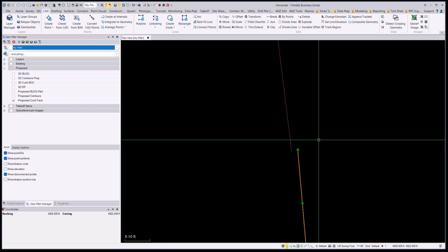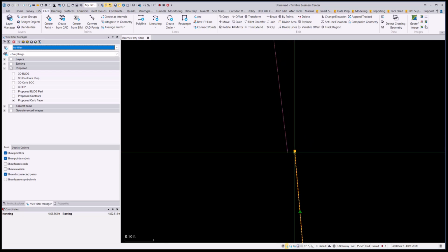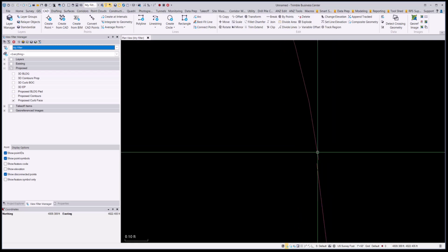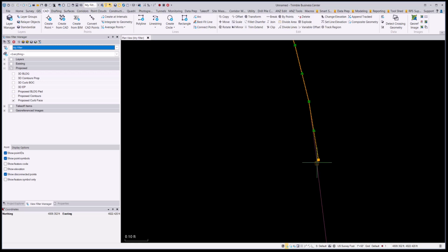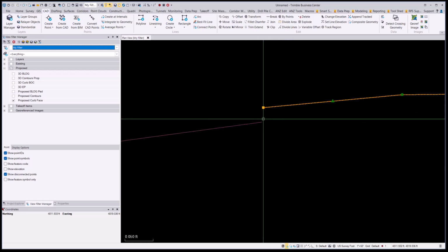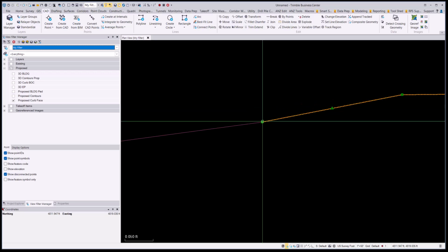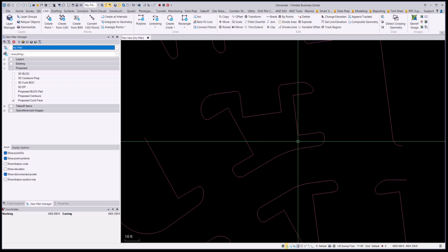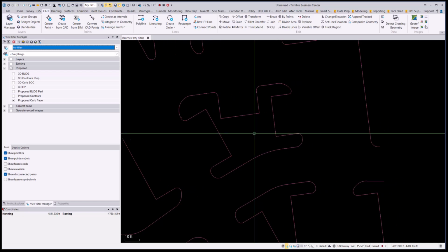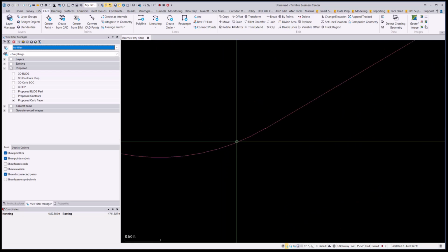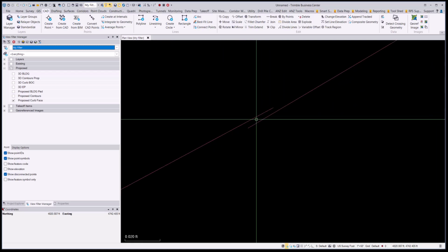So if I wanted to, I could go through all these and I could drag and use these grips, and I could snap these together. And so I could walk all the way through this. And again, you're moving the location of the line, but you're saying, yeah, I'm doing a takeoff, I'm okay with that. All right, or we might force it to close. And how you can force it to close is, you need to know what's going to happen when you push 2 lines together.